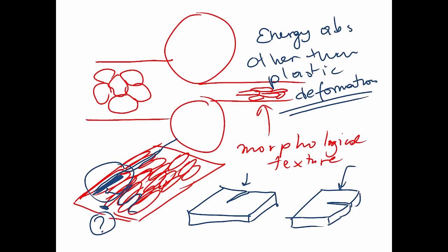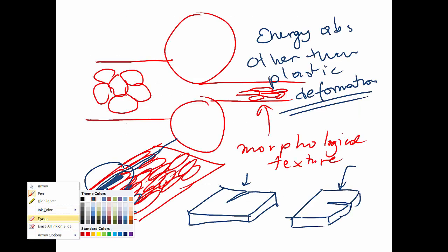Well, before we go there, I just wanted to repeat one more time a couple of the practical things that we can do with the values of fracture toughness that we have. If you have a value of fracture toughness for a material, then you can do two things. First of all, you can say, okay, if I have a certain crack size, what is the stress that will actually make my material fail? And in this case, you have something like this.